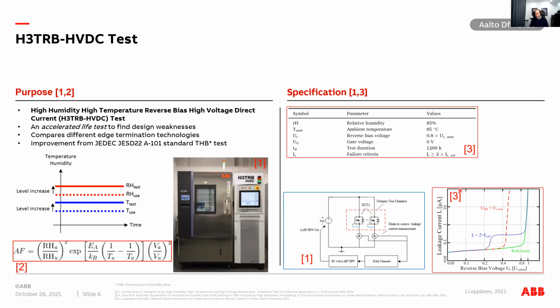On the other hand, with this kind of curve tracer measurements, you cannot do these measurements at high humidity. It's a separate test setup. It has to be always done at room temperature and ambient conditions. So it is not possible to do it at the chamber. Yes, we could build up a setup that we could do it here already in the chamber, but would it give us anything new? Because you cannot study the component itself at high humidity after the test.